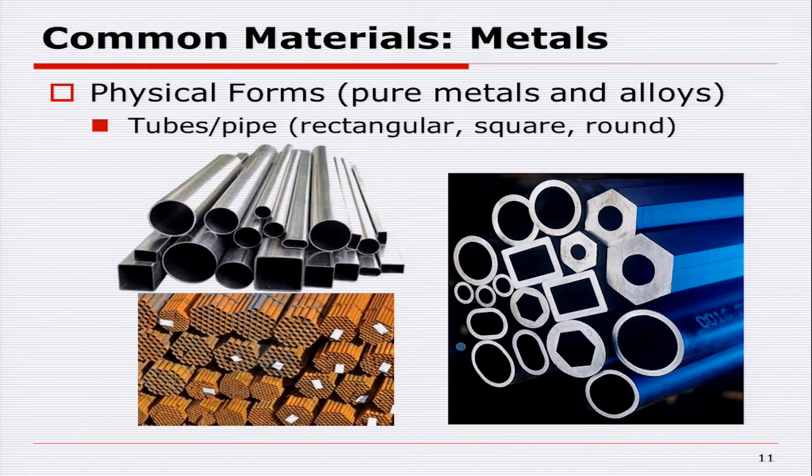round. We have some hex shapes over here, and here are some hex shapes that have a round center to them. And then you have a round OD with a hex interior. So you can actually literally slide one of these inside one of those. Keep that in mind. That's typically a way you can transmit power, for example, but have two shafts that slide one inside the other. You want to spin this one and have that one turn. This is how you'd start using some of these different shapes.